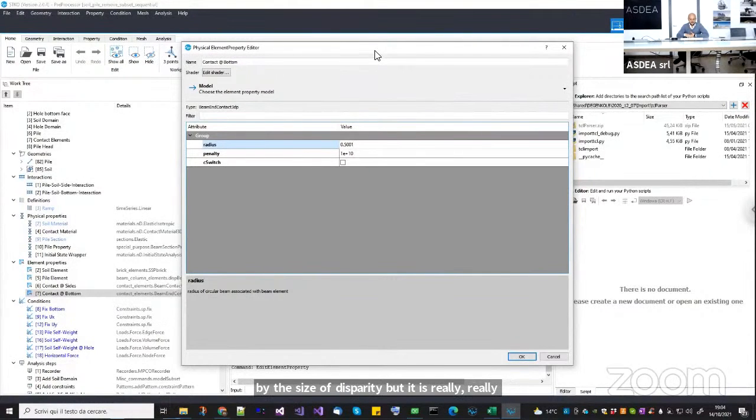There are many papers that explain how to get those values. I typically use something which is close to the shear modulus of the material. And G is not the only problem, because if you take the shear modulus of the material divided by the asperity size, it can be 0.5 centimeters, for example.